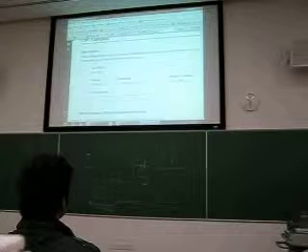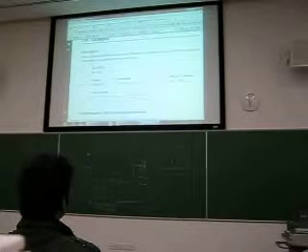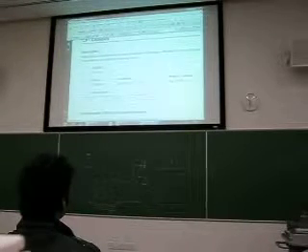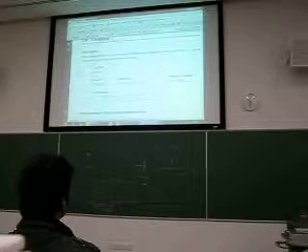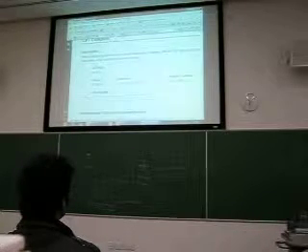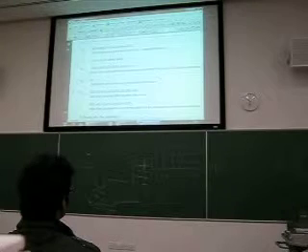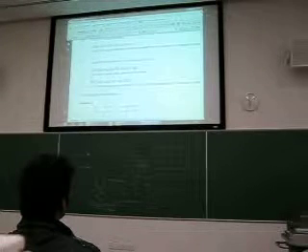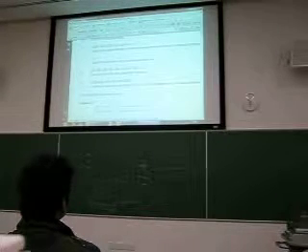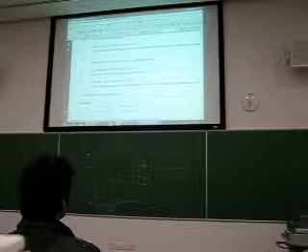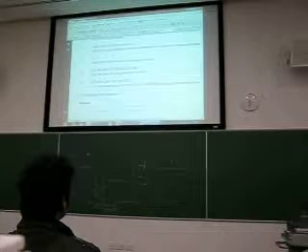RD can be anything. It can be, for example, R1 minus R2. And if that subtraction gives me a 0, I look for the set if the result is 0. That's how I know that my 0 flag will be set. Okay?